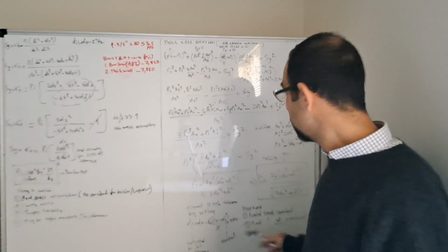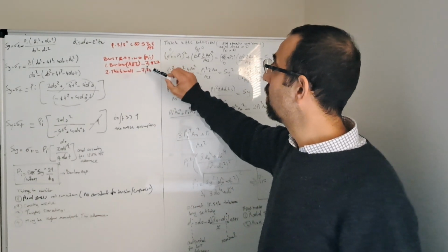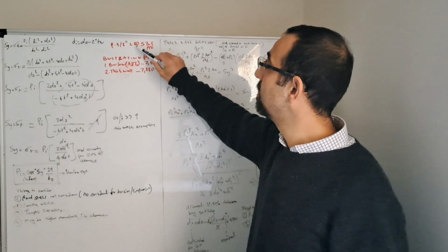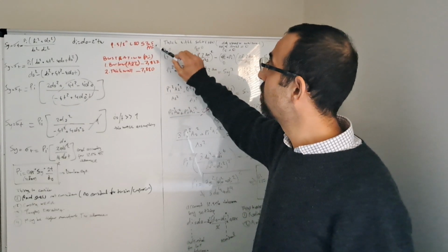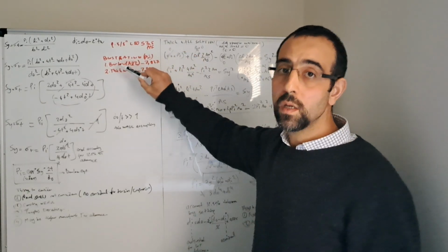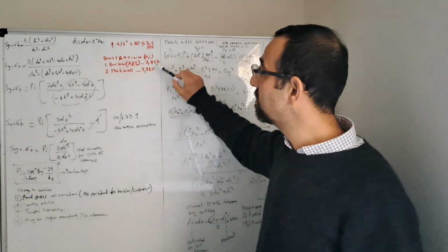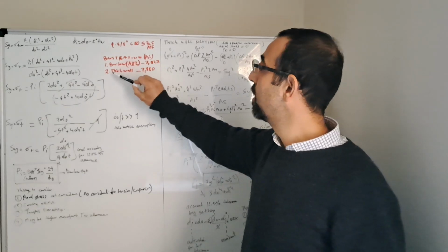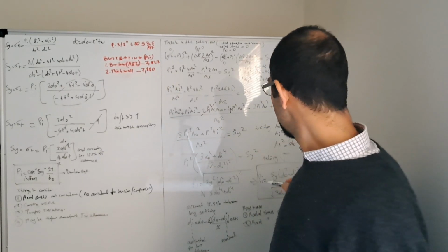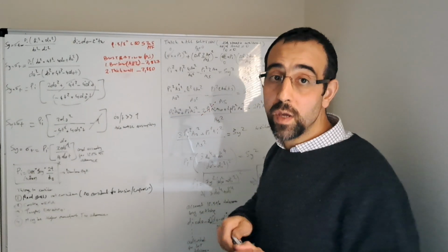And when we look at this one, I just put a number for our interest. For example, for 9 5/8 inch L80 53.5 pounds per foot casing, if you use the Barlow equation, a thin wall solution, we get 7,930 psi. That's the book value, or the spec value. And then when we use a thick wall solution on this one, we will get a slightly lower value when we account for the